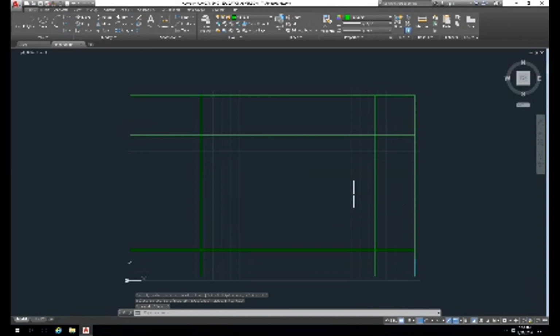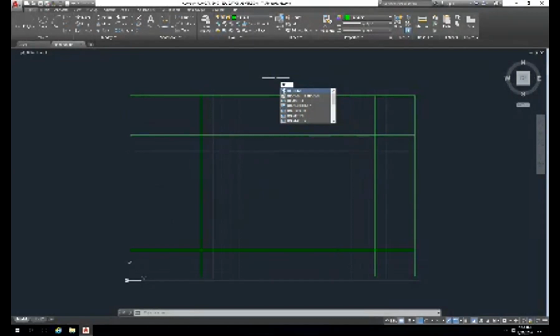So now I'm going to trim. So I have these squares or rectangles, this one, this one, and this one here, which are the outer dimensions of those projections that we want to create from a 3D object. It could be a physical 3D object we're measuring and we're creating this, but in this case, we're following a 3D drawing. So I'm going to use the trim command, and you type TR, and that's what comes up, trim command.